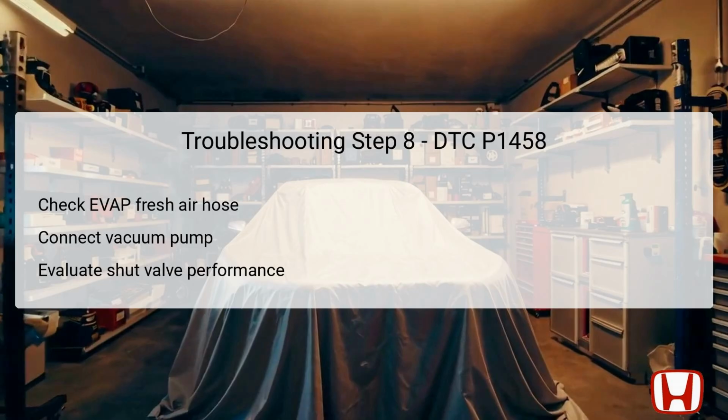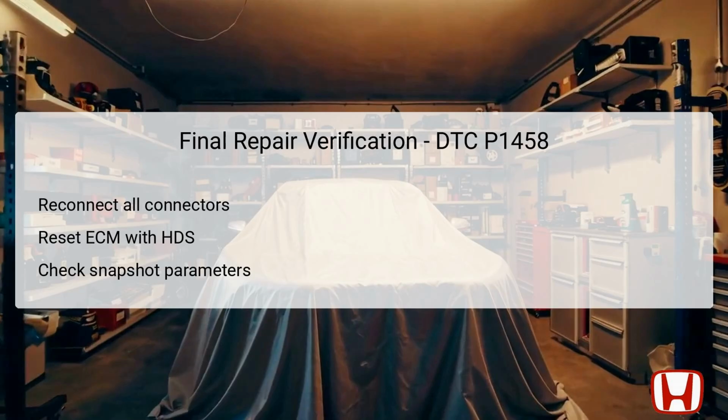If it does, the fresh air hose is deemed operationally sound, and it may be necessary to replace the EVAP canister vent shut valve if issues persist. Conversely, if vacuum fails to hold, removing any blockages in the fresh air hose is critical, along with potential replacement if damages are evident. After completing all necessary repairs, it is crucial to verify that corrective actions have resolved the issue. Begin by turning the ignition to the lock position and ensure all connections are properly reconnected.